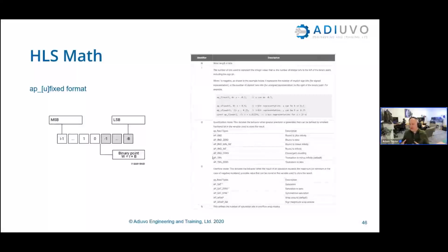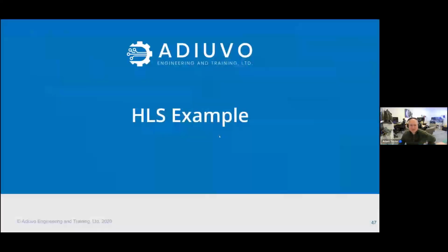So it's a really nice, simple way of doing it. You can see a couple of examples there. For example, with 2, 0, A could be stored as 0.5 because there are two fractional bits in there. So it works really nicely to give us that functionality.